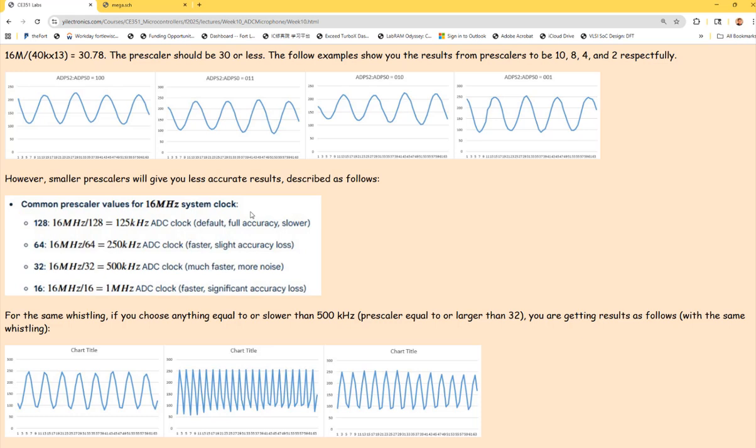You have to know the input signal, what the frequency of it is, then you can choose the sample frequency. So for 25 microseconds, we just did a calculation. What's the sample frequency of that? 25 microseconds per sample. What's the sample frequency? 40K. Is that way larger than 4K? Yes, this is good. It's good enough.